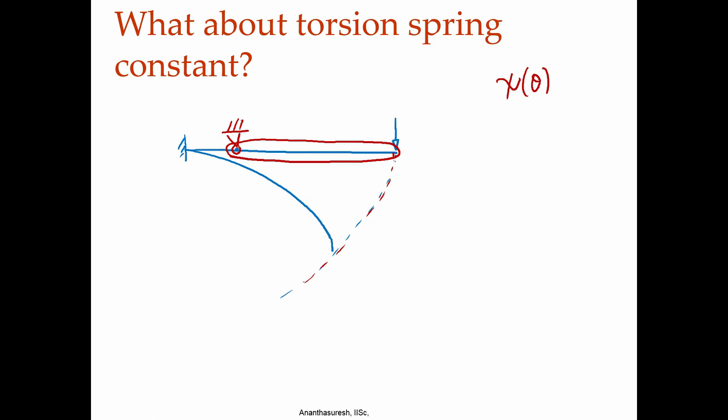But if I were to also consider the relation between force and the angle psi, that is I want to know how psi changes with F, not just psi as a function of theta, which is purely kinematics. If I say psi as a function of F, if that is what I want to know, then I have to get some notion of elastic model in my equivalent rigid body model.